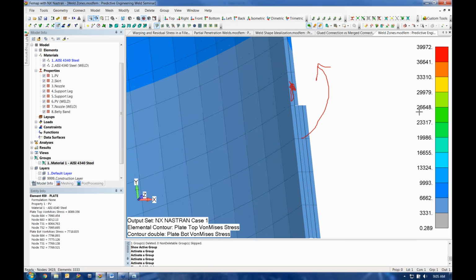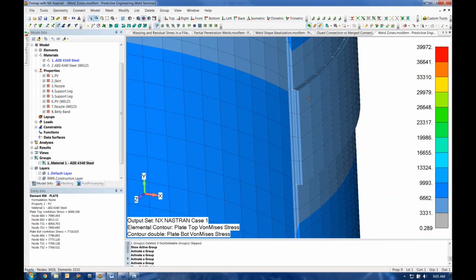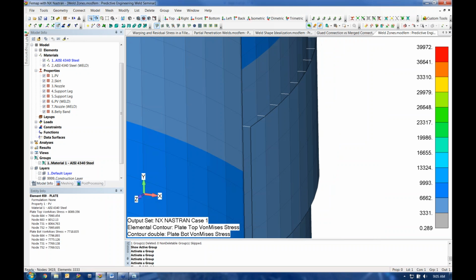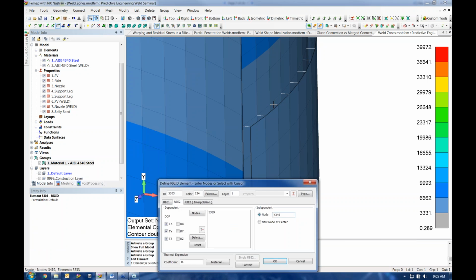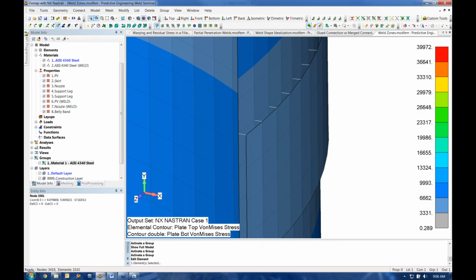So in our model, it's not quite as much of an issue because we have welds on both sides. But how do I actually model that weld in FEMAP? What I've done here, let me turn off my thickness, is you can see these tiny little white lines, and those are rigid elements. And if I edit one of these rigid elements, you can see that it only has the 3 translational degrees of freedom. So we're not allowing that welded connection to carry that moment. Just like that fillet weld, yes, it's going to work well for transferring normal loads or shear loads, but once you start bending on it, it's going to open right up. We're capturing that effect with the idealization of these rigid elements. So obviously you don't want to walk through and snap these in one by one. So let me show you how to set this up.